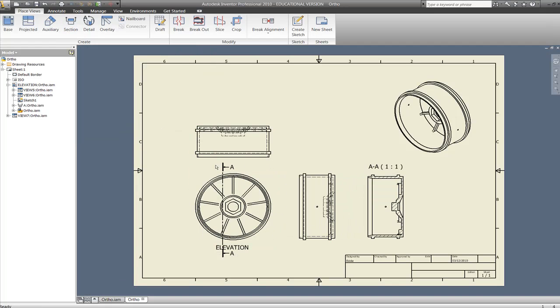One reason that I was careful to draw the cutting plane line off the centre was to make sure that the cutting plane line didn't get locked onto that midpoint, just so that I could demonstrate to you that I can now click and hold and drag that cutting plane line into any new location and the sectional view will regenerate itself, like so.